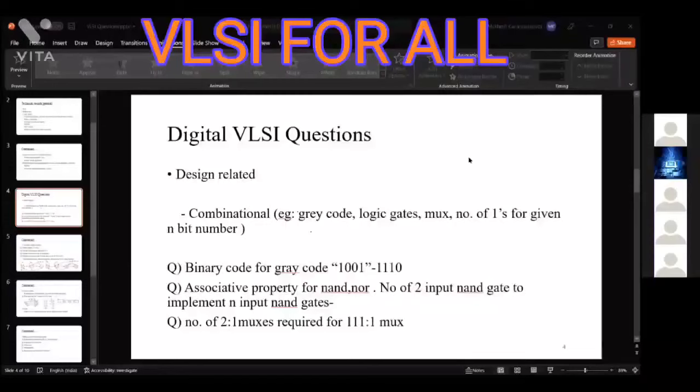For a 6:1 mux using 4:1, you require at least 2 4:1 muxes. The first 4:1 mux will have the 4 input lines, and this is connected to the first input of the second mux. Then there will be 2 other input lines. So overall 6 inputs, a 6:1 mux. It is 2 4:1 muxes, and the last input of the second mux will be 0.